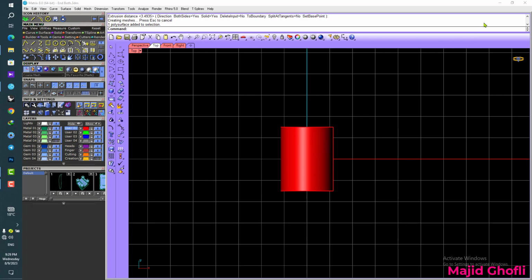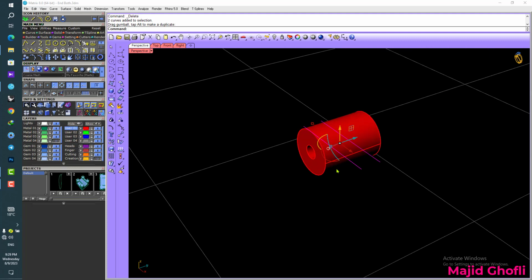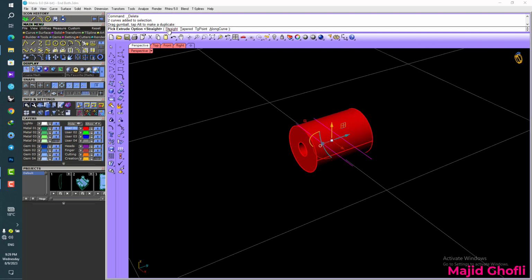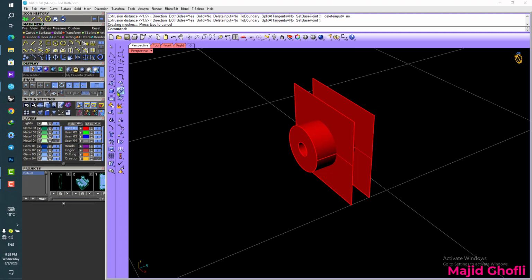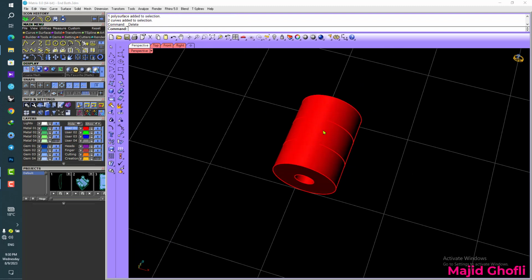So we have to divide the cylinder into 3 half parts, using 2 halves of it for one side of the earring and one middle for the other side of the earring. So see carefully, please. Two single lines to cut the cylinder, and go again to the extrude, and look at this, Boolean Difference, Boolean Split, and it's done. Okay, look at this, guys, it's done.